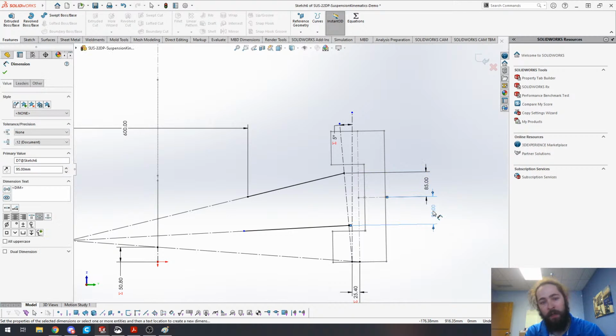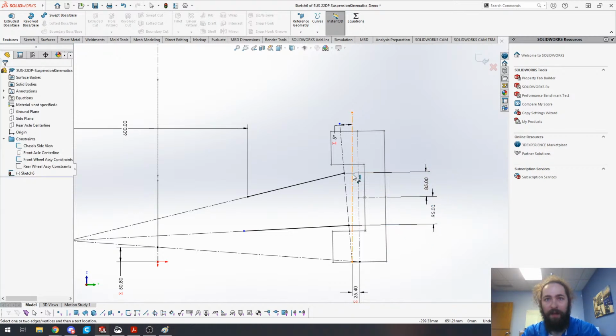So if the suspension designer, or the kinematics designer, is doing things independently from the upright designer, you want to make sure you communicate. RCVD goes into this a little bit, but generally speaking, having these further apart is more desirable. It results in a stronger upright assembly. It also means that if your hole is slightly out of tolerance, it's going to affect the suspension less than if these 2 points were very, very close together. It would have less of an effect on your kingpin angle and the rest of your outboard wheel assembly. So that's something to keep in mind.